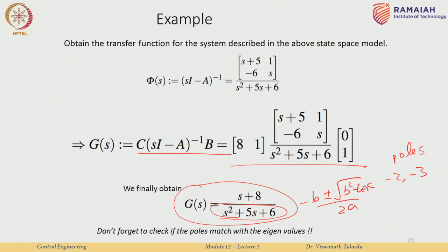And to double check that these poles are correct and that we have obtained them from the correct state space expression, what you can do is compute the eigenvalues of the matrix A, and I will explain why that is true. We already saw a simple example of the mass spring damper that this was exactly the same.